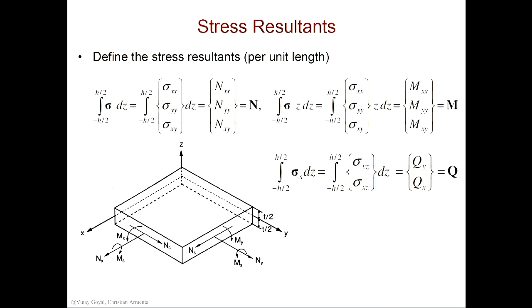So we've taken this stress right here, say sigma xx, which acts that way. We've integrated through the thickness, and Christian is going to talk about per unit length, that this n is per unit length. There's a reason for that: I integrated the stress over the thickness. And so now it's per unit length. So this nxx is actually considered a running line load, as we also call it. Sigma yy gives nyy, and sigma xy gives nxy. So that integral will give you these stress resultants.